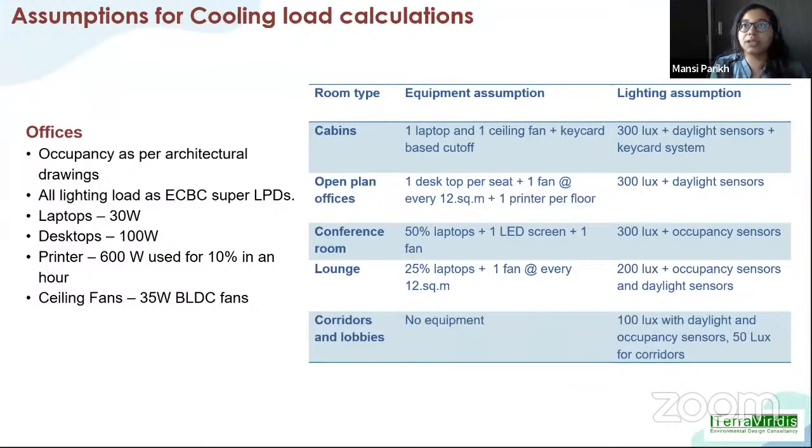So say for a typical office building, for a typical space, there would be internal and external loads. Based on that, the tonnage of refrigeration would be derived. So to get the right size for the tonnage for a particular space, these load calculations have to be done, and the inputs have to be very specific and as realistic as possible to do the right sizing.